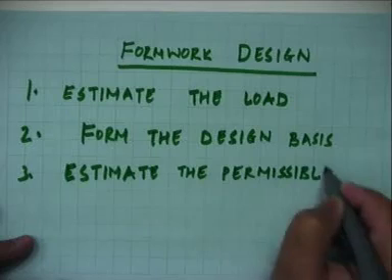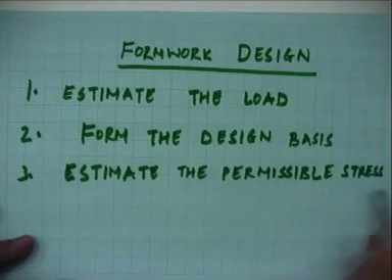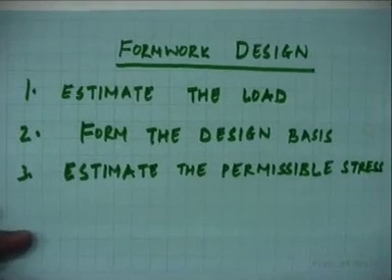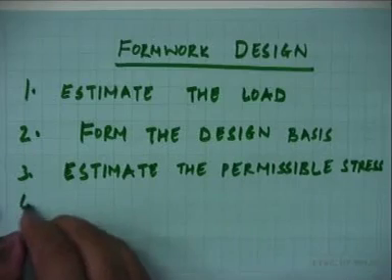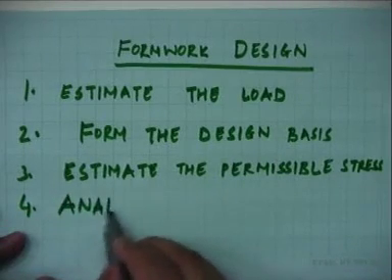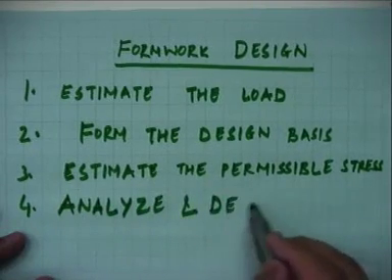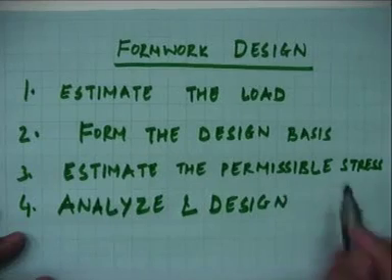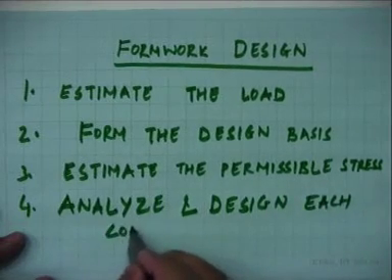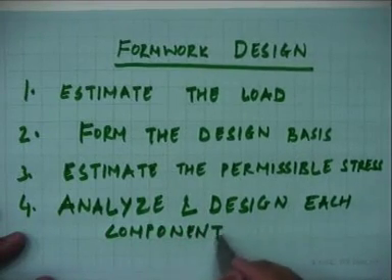For some of the materials I have already given you the values of permissible stresses, both in bending as well as in direct compression and tension. And finally you analyze and design each component. Analyze and design each component of your formwork. So this is a 4-step process.